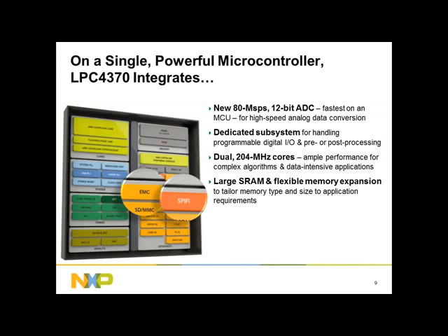You also have your SPI flash interface. Now that's unique to NXP. The SPI flash interface basically connects to a quad SPI flash memory. Now you can get those from a lot of different places, Micron, Spansion, etc. The quad SPI is an inexpensive 4-bit memory, but it's a 32-bit microcontroller. So how do you use a 4-bit memory?